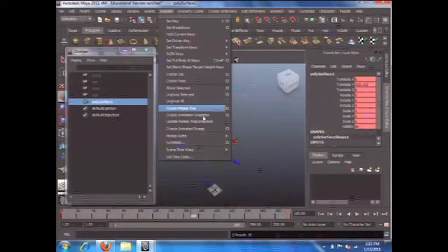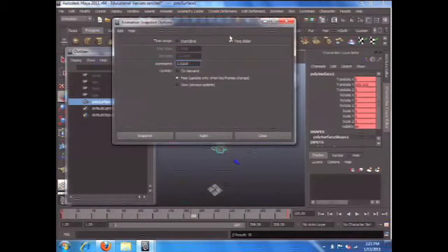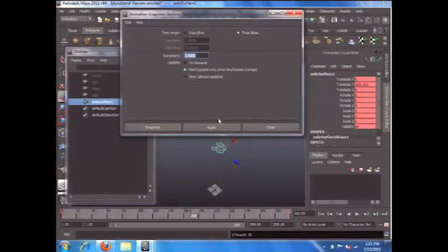Then I can go ahead and make an animation snapshot. So animate menu, create animation snapshot. I will use the time slider. If I want 300 levels, I should choose 1 here, right? But this probably will be too heavy. Let's try 3. So we get 100 duplications, not super heavy. So hit apply.